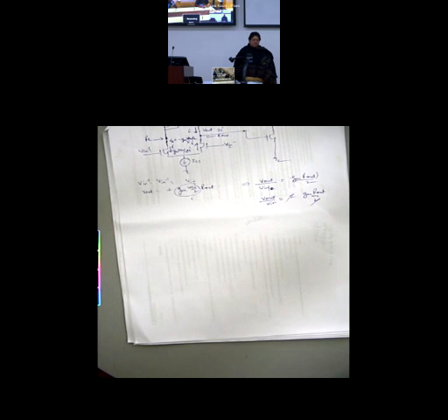A PMOS current mirror load. It is not setting the bias current. No, it is not setting the bias current. It is only acting as a load here. Current mirror load. Now we call this a differential pair with active load.